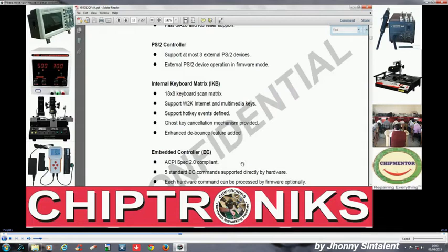There are 2 kinds, 8048 and 8042. 8048 is inside the desktop keyboard and 8042 is on the motherboard, inside the IO controller, right? So when we press A, both those wires get touched, the circuit is completed, current flows and goes to the 8048 keyboard encoder. Kindly note, I am saying keyboard encoder. The keyboard encoder is inside the desktop keyboard and the keyboard controller is on the motherboard. So the current flows, right?